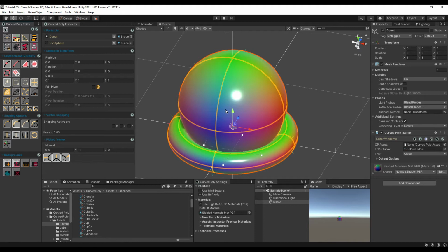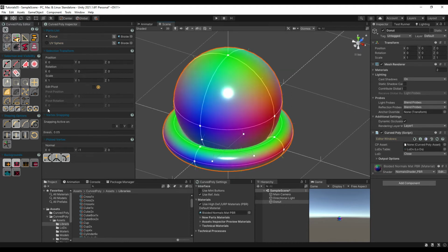It is very practical to know that you can execute the same actions with the S key for Select All, and with Shift plus the S key for Unselect All. Another useful action is Grow. Grow is used to add to selection every element adjacent to elements which have already been selected.